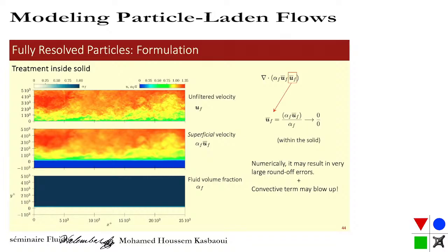All right, okay. So I think I've got another answer for you. With my approach, it's a filtered approach, right? So even if you do AMR to try to resolve near the surface of the particle better, the solution is going to be controlled by your filter size. Just because you throw more grid points at it doesn't mean you're going to get a better solution, because it depends on the filter size.